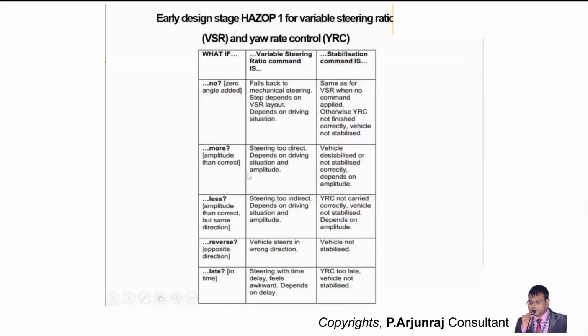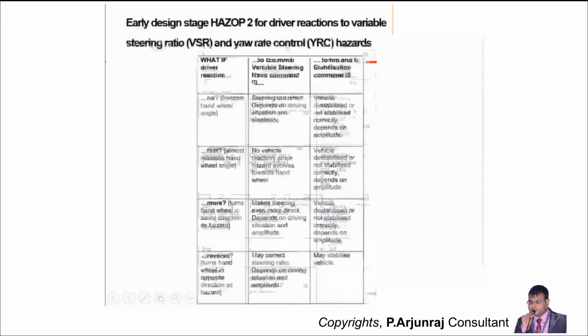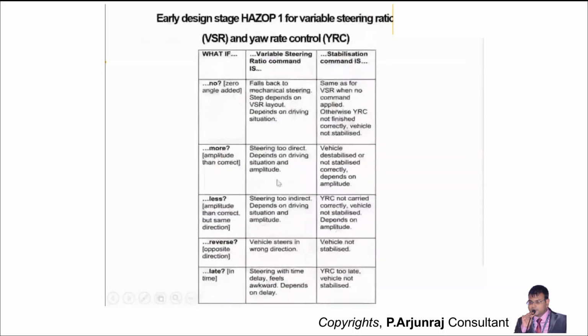That's why it's very important to arrive at the detailed explanation with respect to the second level, considering the driver reaction. It's very important that you analyze at the first level, considering the command and also the requirements. This is where the uniqueness also comes. You're asking for the DFMEA, FMEA. Here, you consider all the functions and you look at the malfunctions also, what can go wrong. With those malfunctions, again, you derive some of the requirements that should be a part of your safety design, or your item definition.